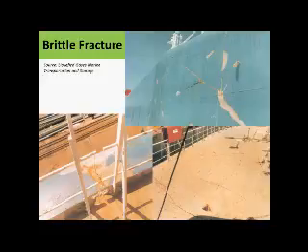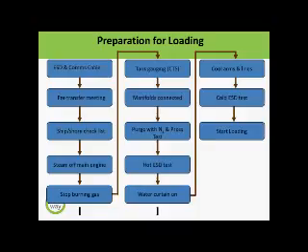And then this is what we have got: ESD, comms and cables, pre-transfer. Now we are doing the preparation for loading. We will do the emergency shutdown test, the pre-transfer meeting, ship shore safety checklist, steam to main engine, stop burning gas, tank gauging, manifolds connected, then purge with nitrogen.